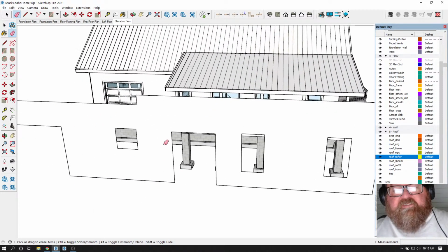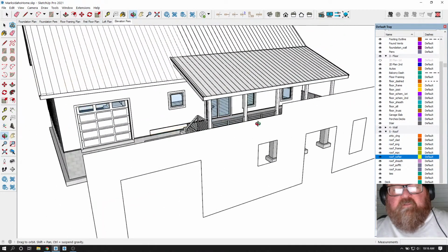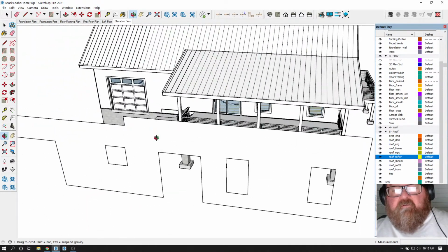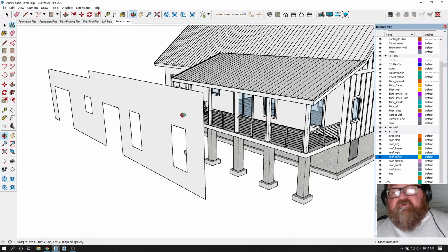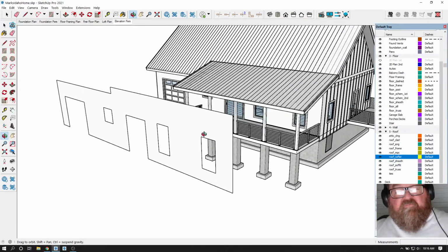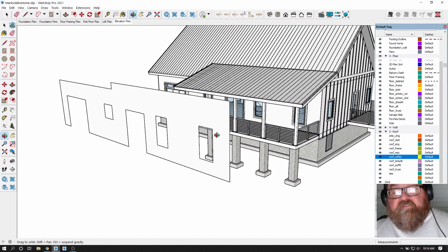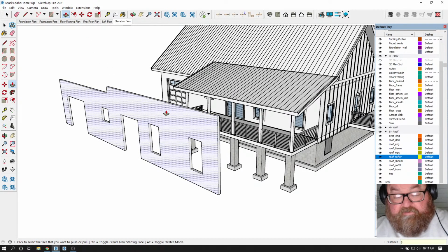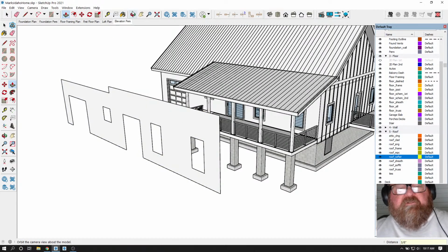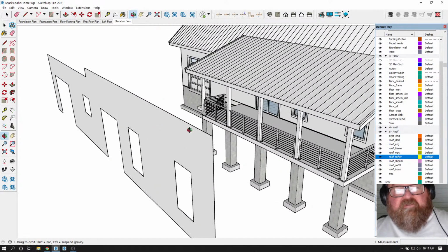Now, I wonder if it's easier. The problem with adjusting these openings before I put the battens on is I don't know exactly where the battens are or where this opening is in relation to the window trim, so it might be just wasted time. That's why I found in the past it's easier just to go ahead and make this siding. It's nominally 3/8 of an inch thick, but it's really only like 5/16.